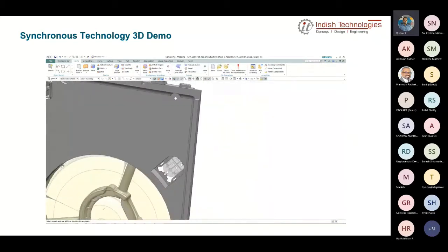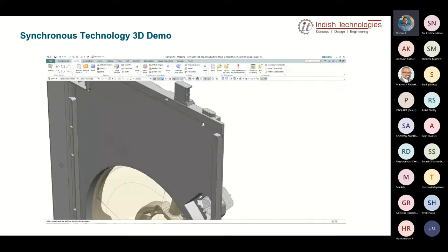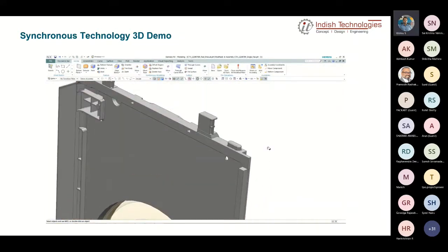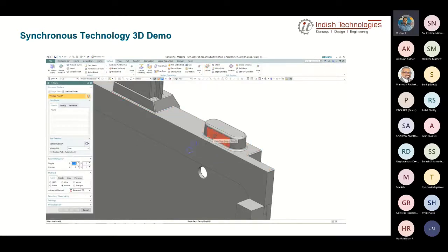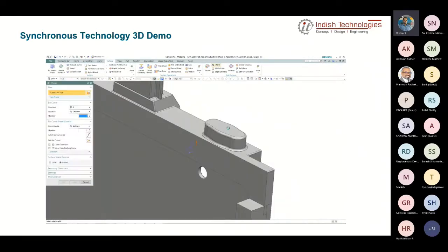Another interesting feature is the X-form or I-form, which can be used to manipulate surfaces in a free form fashion. So when you consider this analytical boss, you can select the faces, then you can parameterize it based on your requirements, and then you can work on the nodes and the control points to generate a free form surface. So as you can see, when the change is being made on one side of the model, the symmetric side of the analytical boss is also being changed accordingly. Now, this is something called design intent, where the software automatically understands based on the way it was modeled earlier.